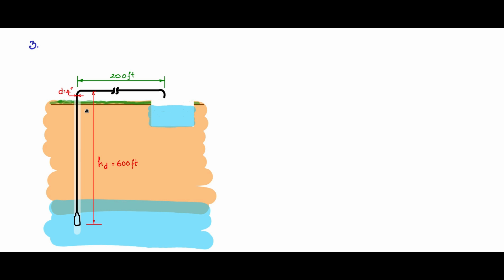You also have 6 inches dia, and depending upon the amount of water that you need to discharge, one will choose the dia of the pipe. So this is the borewell system that we will try to look at. One important thing is that for a submersible pump there is no suction head. Hs is equal to 0.